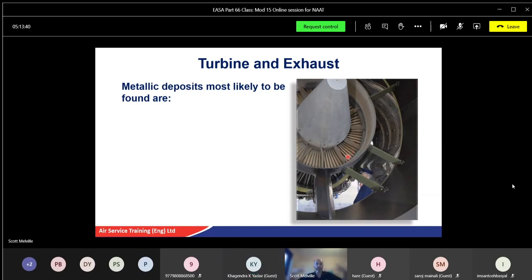And now, some cones also have a hole beneath that cone. Yeah, it will do. Access as well. Yeah, right there, yes. You have obviously the hole. Sometimes it has a leakage of some lubricant. It can do, because that's the bottom of the engine. Now behind that is your turbine disc, your rear bearing, and if the seal is leaking, oil can go into the cone, and you're quite right, that'll show an indication of oil.